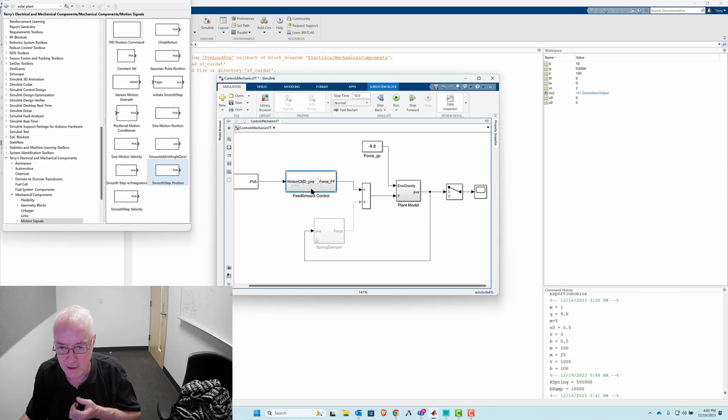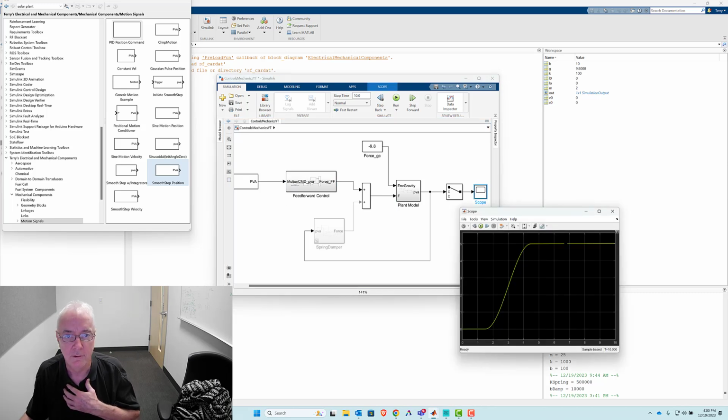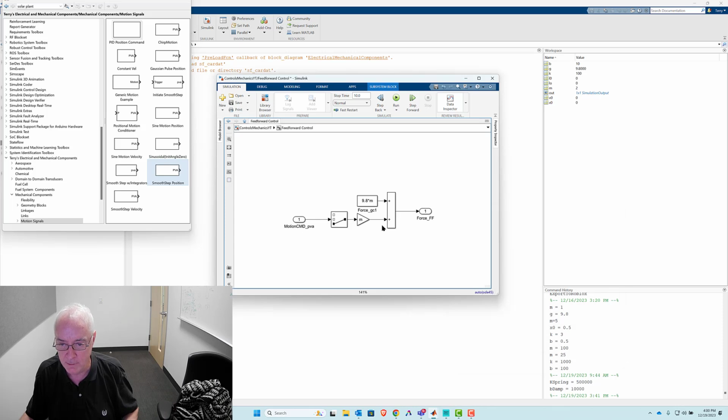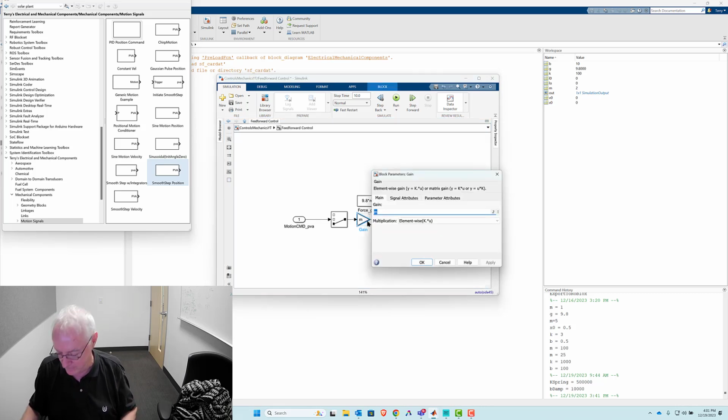And here's kind of the secret to feed forward control. You get this kind of perfection when your information is perfect. It can be kind of easy to be perfect when you're creating plant models in Simulink and you're creating feed-forward controls in Simulink and you're making all the same assumptions. But in the real world, information is not anywhere near as validated as that. Our confidence is, and I'll say even our accuracy to do this isn't nearly as perfect. So anyways, I'm going to introduce some imperfection here.